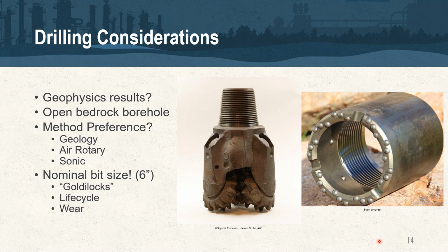Sorry about that, everybody. So the other thing to consider too is now we've selected areas based upon our CSM or our geophysics that we want to possibly install an additional well. Again, when it comes to the injection, we need open, uncased, unscreened boreholes to use these packer and characterization setups for both discrete sampling and geophysics.